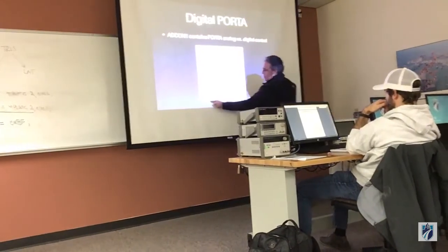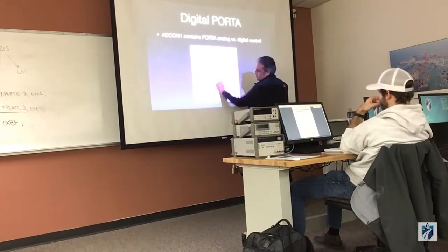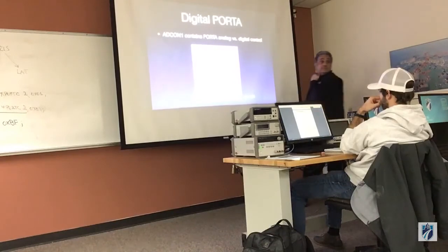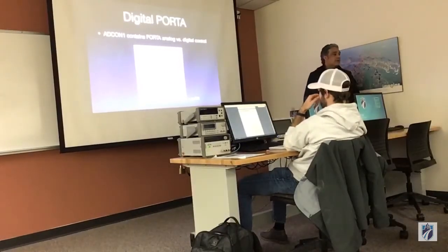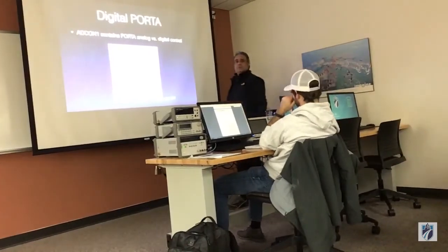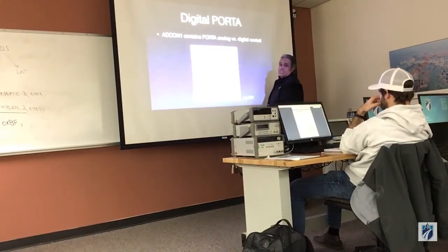Look. If I put an F in these bits, I get 1, 1, 1, 1. That means that every single pin in the microprocessor goes to digital, including the 5 pins in A. See that? Here's the problem with this micro. This micro does not give you individual digital control. It is sequential digital control. So if I want A1 to be digital, you have to make A0 digital too.